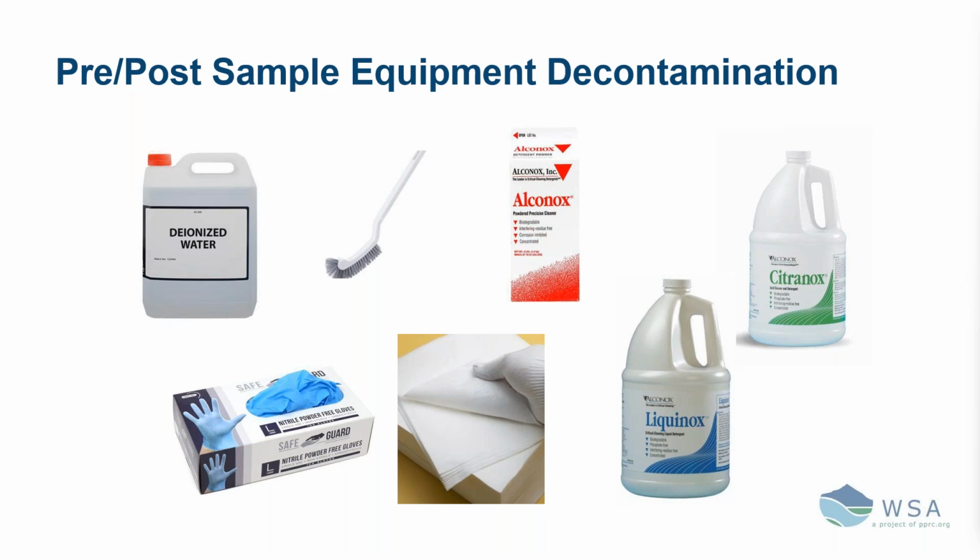So pre and post sampling equipment, again, your deionized water is the preferable water for use, a nylon scrub brush, your nitrile gloves, cotton towels for wiping anything down. And I use a 2% solution of Citranox, but the approved cleaning is Alconox and Liquinox as well.